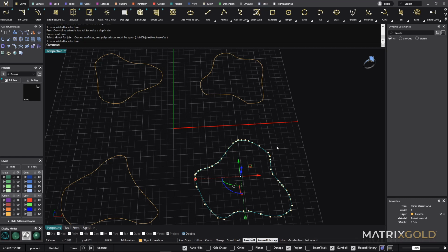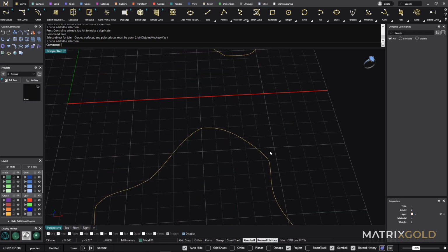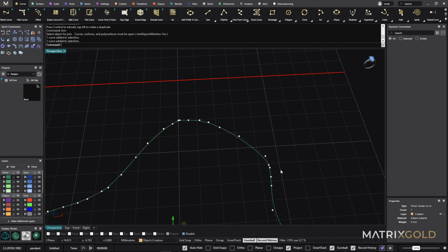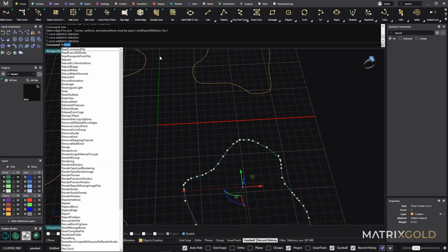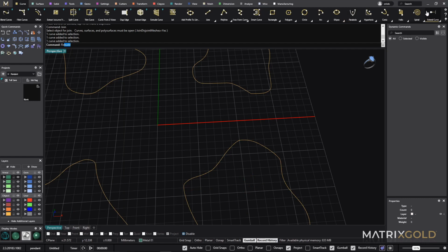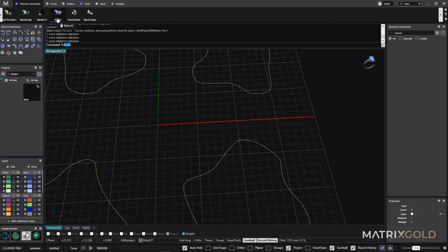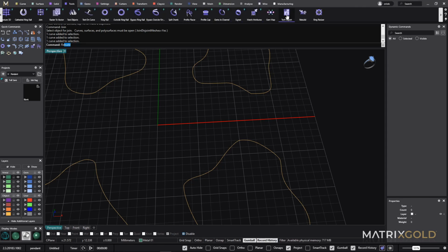Anytime that we see that we can make a smoother curve, which will bring us less problems, we can do that with a rebuild. So now, there is this part here that maybe has these 2 points, so what I can do is just go to the rebuild tool. You can put it into the command line, or also you can go to the search and see what it is. We have so many tools that sometimes it's hard, but you see I have it here. So actually it must be in tools. So right, so if I close it here and I go to tools, the rebuild is here.